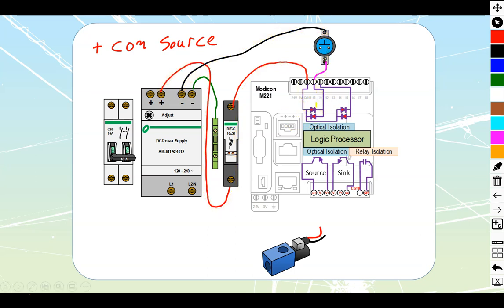The danger with this is if there would be an accidental crushing of your cable or an accidental grounding of your cable that would happen right over here, we would now have an alternative path from ground through the can back to ground over here.